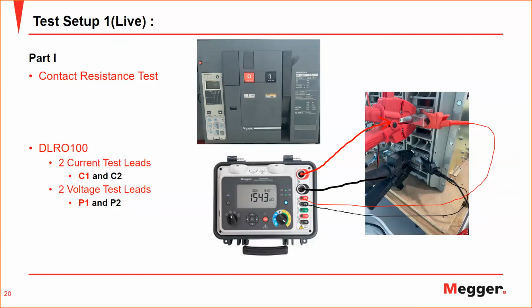So you have to isolate, open the breaker, isolate, and connect earthing contacts. The one thing I would recommend is to try to do dual ground measurement, where you will inject current in both. It will be going through both the main contact loop and also the earthing loop itself. And you will be measuring only the current flowing through the main contact, because you will connect an additional clamp through the earthing loop to subtract that current.